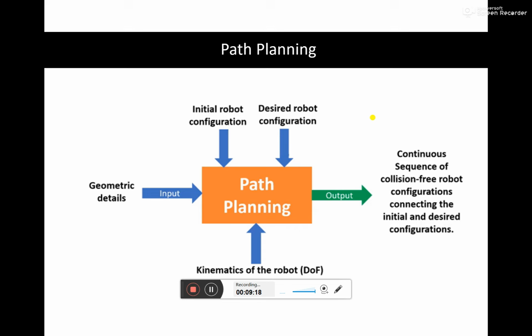After that, you will plan and execute the program, or you may use a teach pendant, or you can give some program to the robot. Accordingly the robot will perform, and because you already planned it such a way, the robot movements will be performed without any collisions.